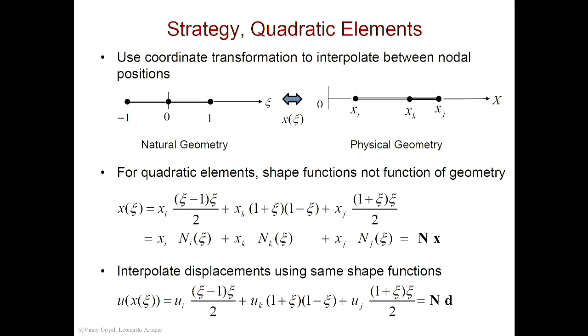So let's see if this works, because we need to check it. And I'll walk you through this. So this shape function right here, let's see if I get what I need to get. At minus 1, this node needs to map to this node. You agree? That's what we want. So if I plug in minus 1 here, you agree that these are 0?